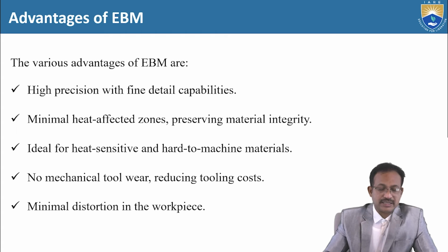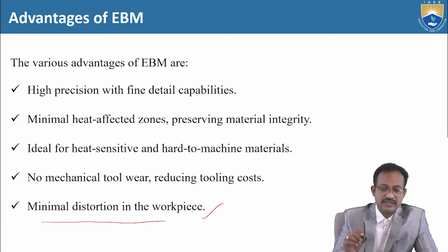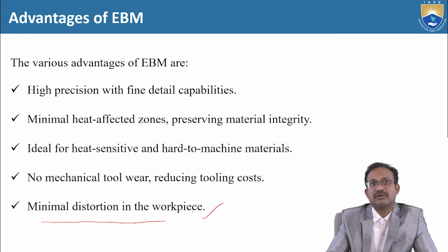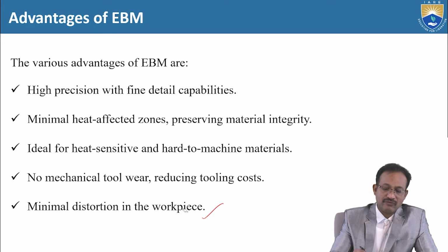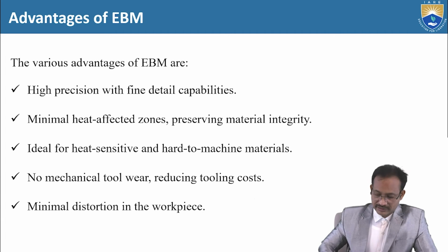Next, minimal distortion in the workpiece. There will not be any vibrations. There will not be any heat affected zone and there will not be any thermal stresses involved. So minimal distortion in the workpiece. There is no big scope to have unwanted stresses or hidden stresses in the workpiece material during the machining.